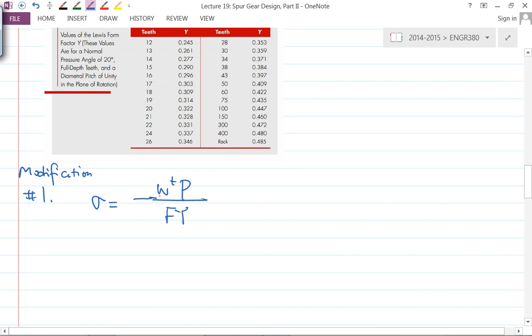When gears are in contact with each other, the fundamental objective for gears to engage each other is to ensure a constant velocity ratio. But you don't get to maintain that often, actually. Often when you have a gearbox, when you drive a car, you hear some clunking noise. So what caused that? When that happens, you don't really have a constant velocity ratio at that stage, and there are different reasons.